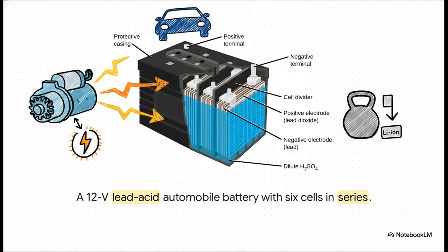Now compare your phone battery to your car battery. The workhorse of the automotive industry is the lead-acid battery. It's heavy, it's caustic, and it essentially strings 6 2-volt secondary cells together to get 12 volts total. Sure, they weigh a ton compared to lithium-ion, but they are still the absolute standard for cars because they can reliably dump that massive, sudden surge of current you need to crank a heavy starter motor.